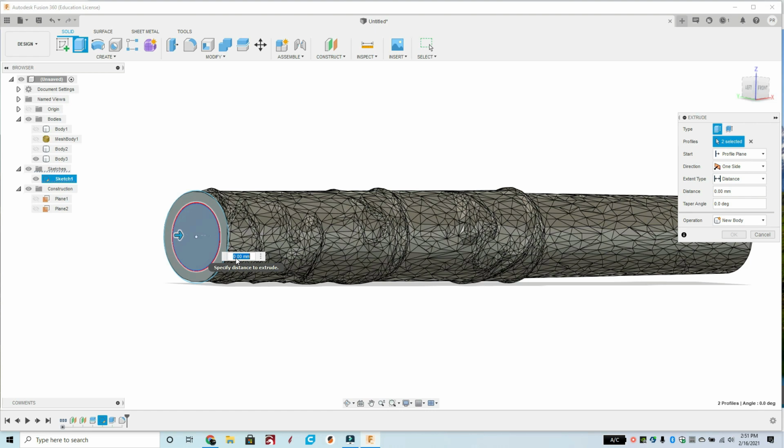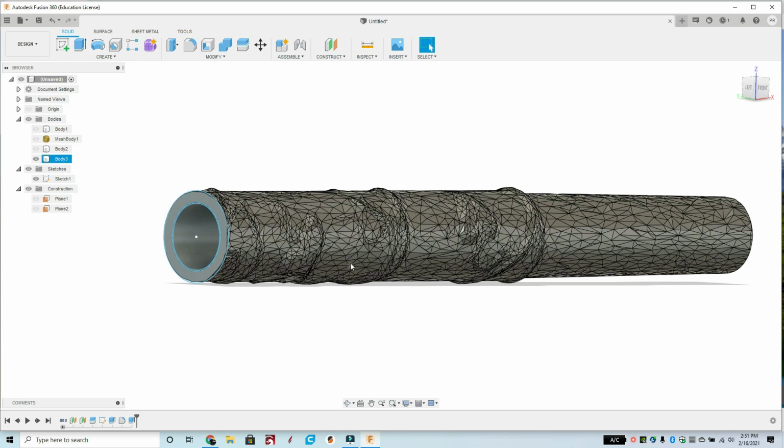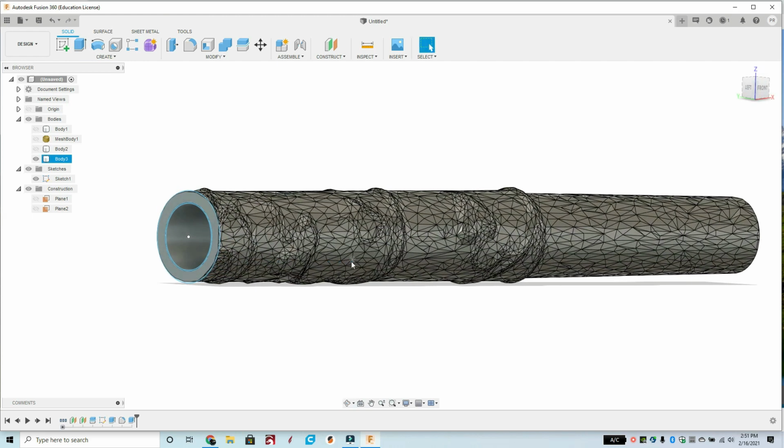So I'm going to do 10.5, and if you see, that's red, and now it'll say cut over here. So that is extruding into the base of the wand. Notice I did, instead of 10 like the peg, I did 10.5 to give plenty of room, and plenty of room for some CA glue if that's what you're using. And then hit OK. And now we have the hole.